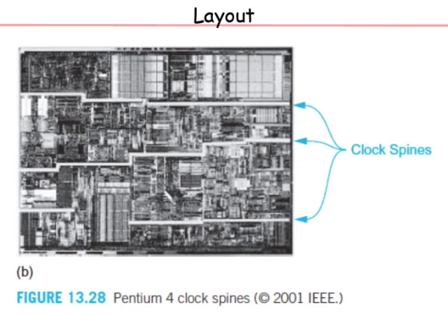Some early chips did that, but they consumed so much power, because you are having this large metal grid going up and charging and discharging at the clock rate, like a few gigahertz. So that's why the clock power consumption is quite high, and people look at various techniques. They break it up into global clock distribution, which is what we are seeing, and then local clock distribution. Local clock distribution we'll see in the next slide.